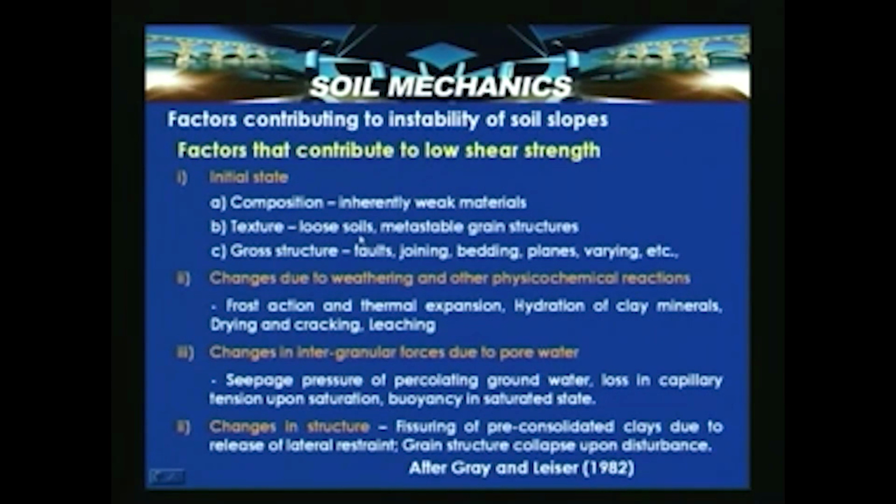Texture, loose soils and metastable grain structures, like a honeycombed grain structure, can contribute to low shear strength. And gross structure like faults, jointing, bedding planes, warping, etc.